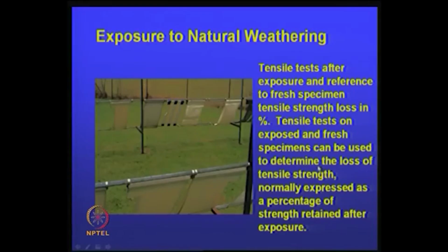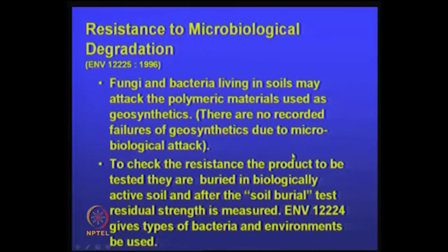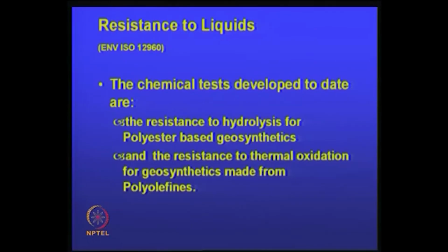So, you have to really do some testing here, which is very important. Then you have what is called resistance to microbial degradation. Fungi and bacteria living in soils may attack polymeric materials used as geosynthetics, and of course there is some test. The advantage is that we bury them, so the exposure to the outside is less, but even there is a possibility that some microbial organisms could attack. So, that needs to be examined.